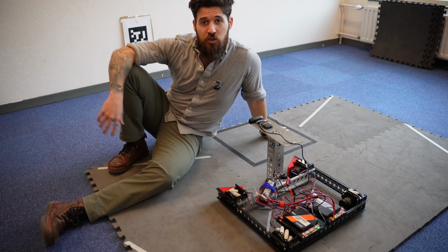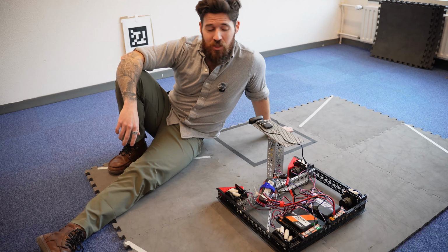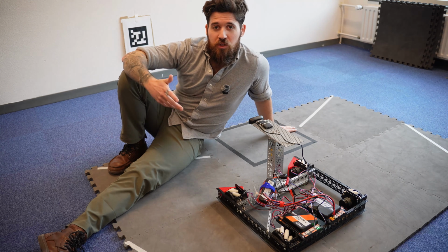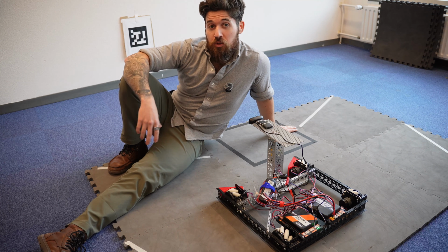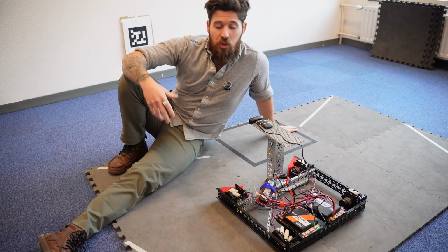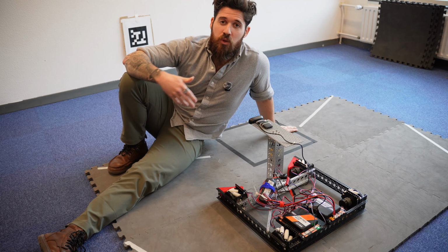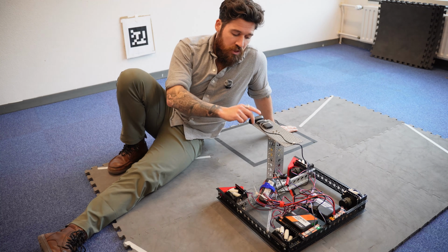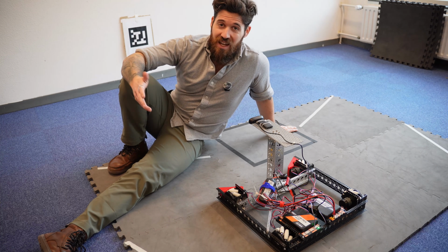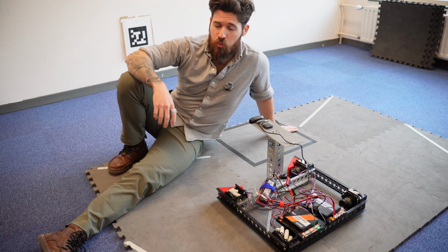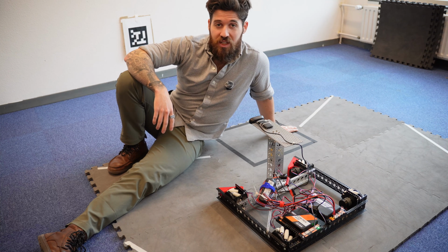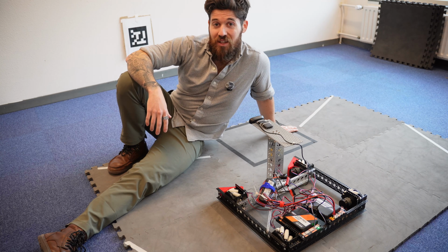My P value might still be a little bit high here. But realistically, you could tune your P and your D controllers until the cows come home. I think for the purpose of this tutorial, that's good enough to get you off to the races where you can do your own tuning. Effectively, you want to get your P up to a point where you're not overshooting your target. My P is still a little bit high and I am overshooting that target. Also keep in mind, if you use a different motor setup than me, you'll probably end up with different KP values and different KD values as well.